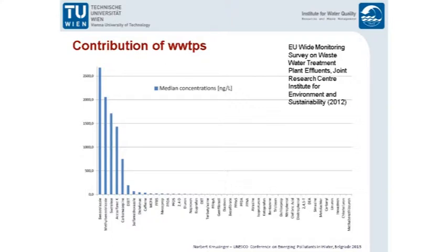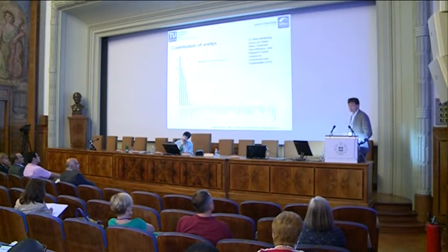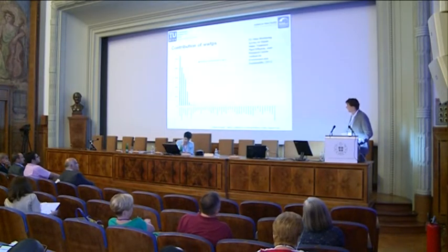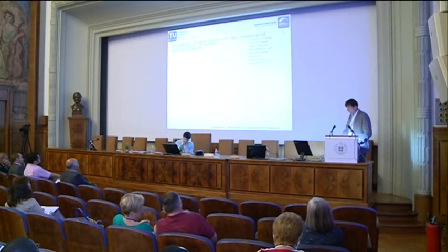Again, artificial sweeteners are designed not to interact with the body. They are zero-calorie sweeteners, so the body does not know how to deal with those substances. And the bacteria in the treatment plants do not either. So they just leave the wastewater treatment plant in the same concentration as in the inflow. And of course, in the surface waters, again, we have no biological removal of those substances, maybe a bit of photodegradation. Then we have the carbamazepine, and all other substances are in the low nanogram per liter range here.